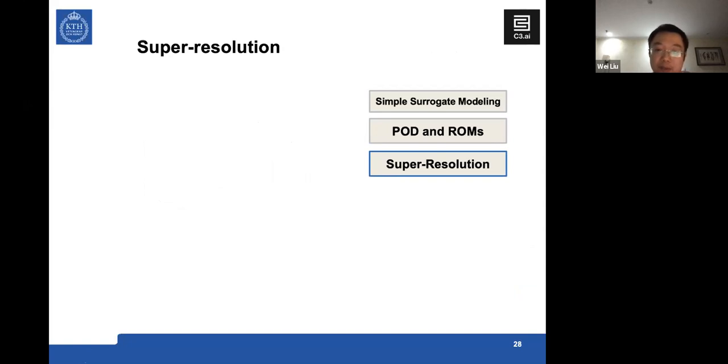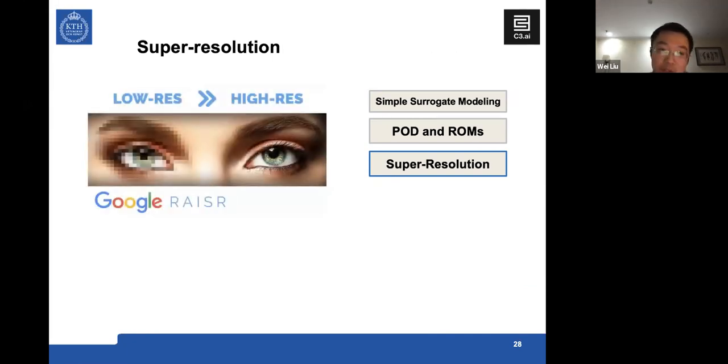And amongst the benefits that the data-driven model brought to fluid mechanics research, super resolution is a preeminent and new one for the analysis of fluid mechanics problems. Borrowed from computer vision and image recognition, super resolution imaging refers to the class of techniques that aims at obtaining a high resolution image output from a low resolution image input. The same concept could be applied to flow fields by treating the flow fields as just an image.